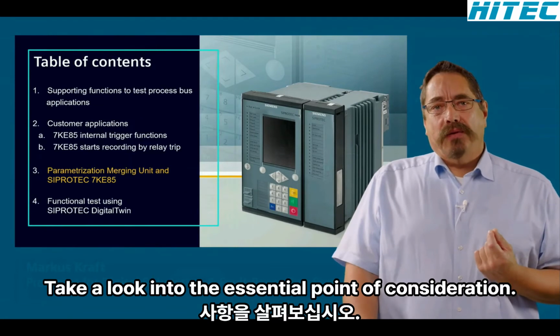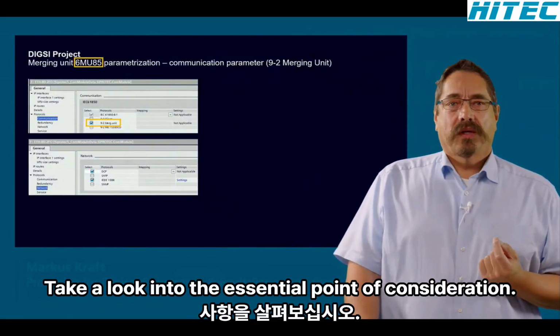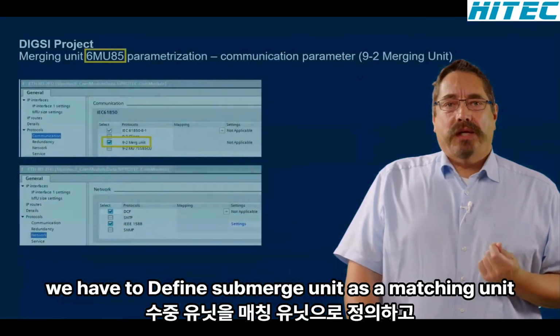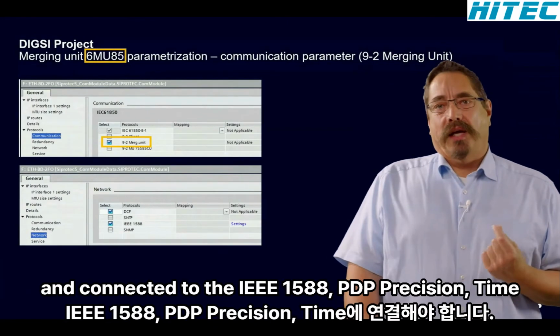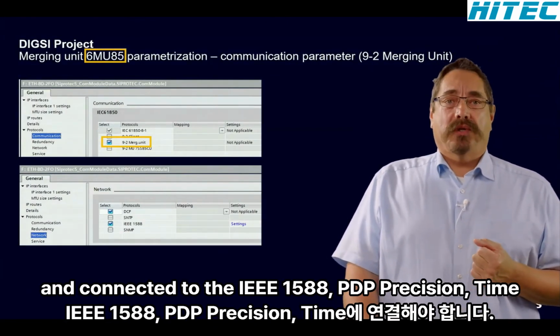Let us now take a look into the essential points of configuration. On subscriber side, we have to define the merging unit as a merging unit and connect it to the IEEE 1588 PTP Precision Time Synchronization Protocol.